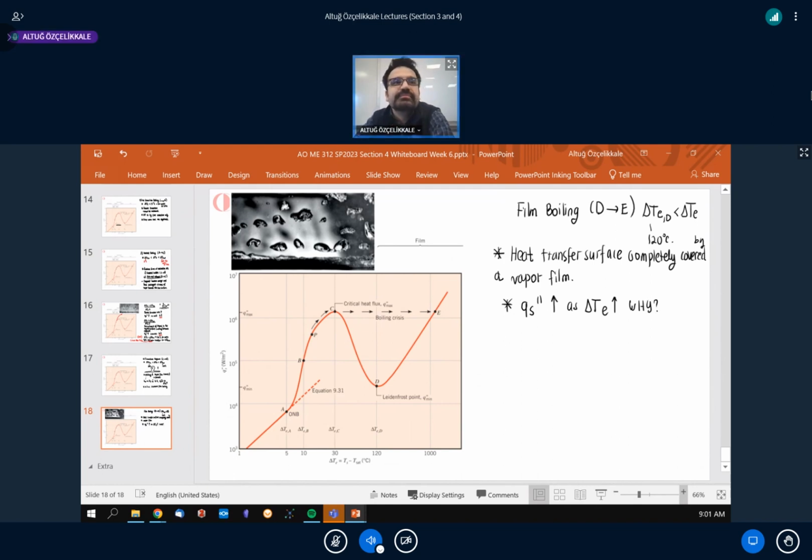Any guesses on that? If you are following this from the textbook, it's already there. So what you can reason about that, right? Look at the temperature range here, 120,000, that's a logarithmic plot. We are actually having quite high temperature values here. And remember that one of the modes of heat transfer was particularly important for high temperatures, like astronomically high temperatures. This was thermal radiation that we are going to be talking about in the second half of our semester. And that's also the reason why we are going to have effectively enhanced heat transfer. The heat transfer by radiation becomes important.